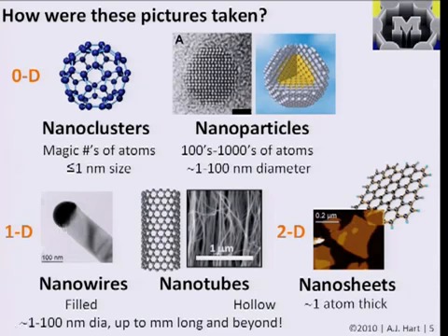And then how about this image in the middle here, this bunch of carbon nanotubes? SEM. SEM image, exactly. Now we're not looking at an individual structure, but at a collection of structures. You couldn't really get a TEM beam to penetrate through this forest. In this case, the electrons are scattering off the material, and that's how we're generating the image. And how about this image down on the bottom right?